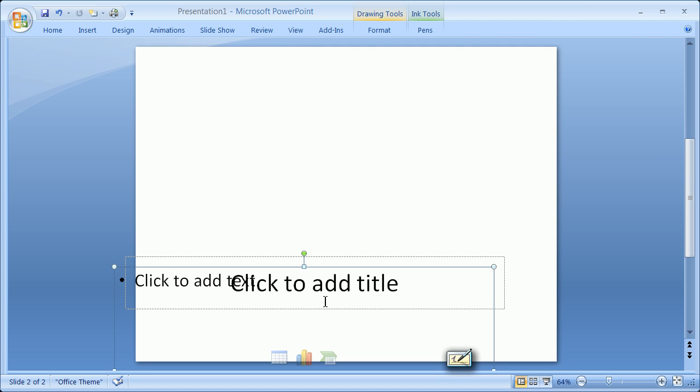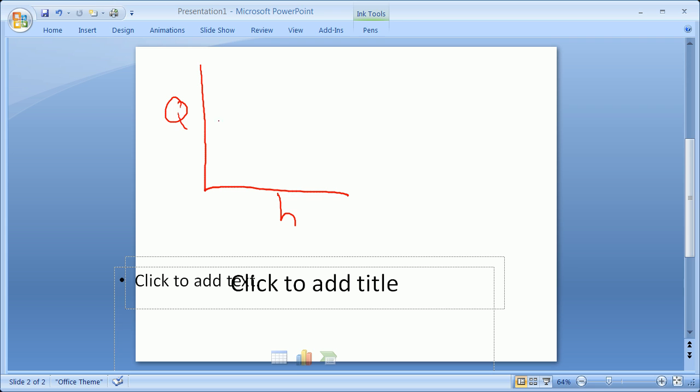All right, so you have to remember that pump curves, as they are known, graph head versus flow rate. If there's a given pump and there is no head against it, it will push out a certain amount of water. They can only go so fast. The more head there is, the farther down you go. So based on the head, they flow, and this is typically in gallons per minute, is the way these curves work. So depending on how much head they're pushing against, they pump a different amount of water.